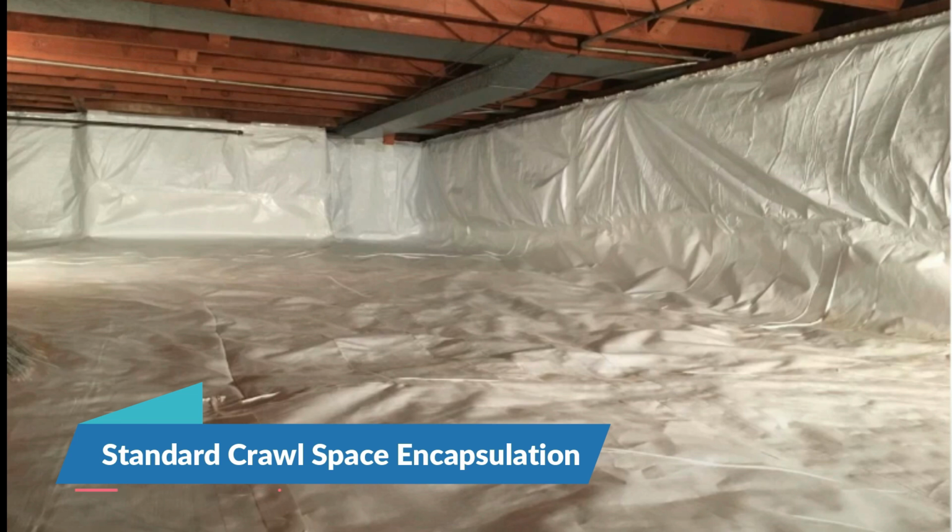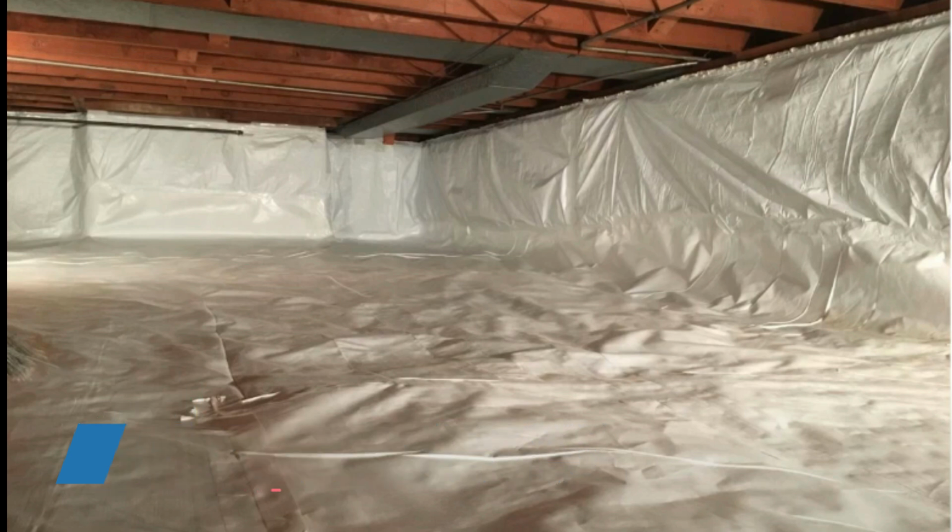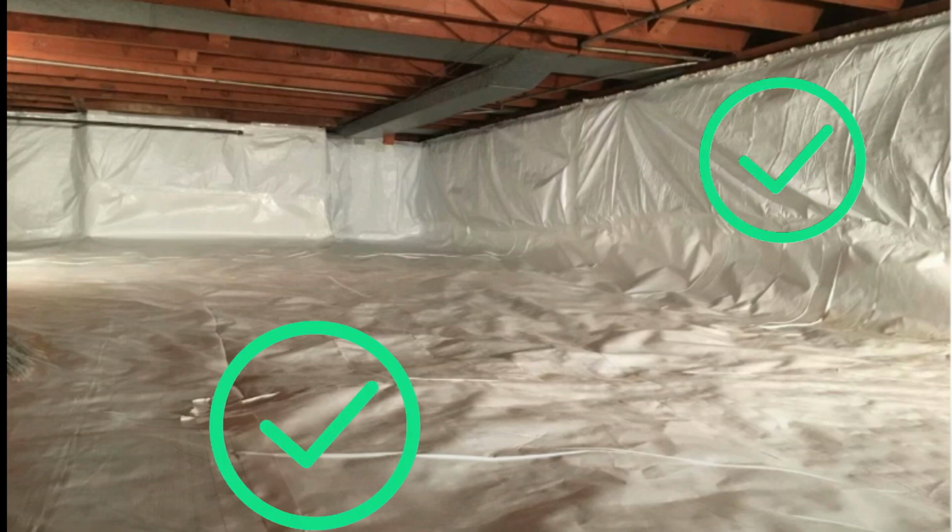In reality, taking into account the fact that the crawl space floor is never perfectly level and the fact that you can only stretch the vapor barrier so much, this is a solid encapsulation. With this crawl space encapsulation, we have a good vapor barrier on the floor and the walls. The issues related to air infiltration have been addressed not just from the outside into the crawl space, but also from the crawl space into the living space.